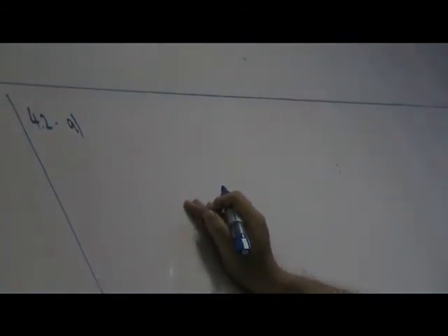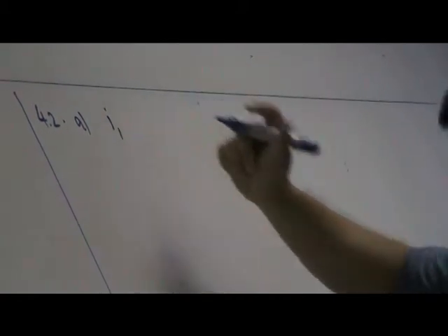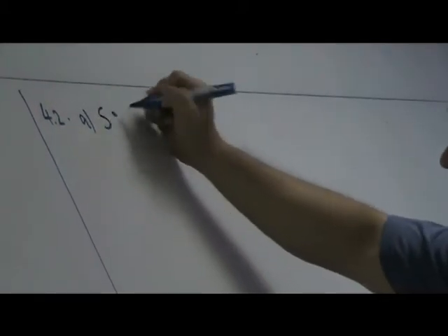Okay, so now for question 4.2. We have a 100 kVA, 11,000/2,200 volt, 60 hertz transformer. We are supposed to calculate the full load rated currents on the high voltage and the low voltage sides. So we are supposed to find I1 and I2 of the transformer. So we have S equals to